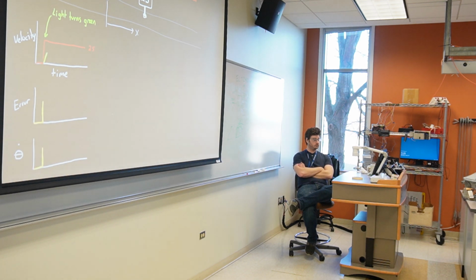Now, as your velocity increases towards 25 miles per hour, your error gradually gets smaller and smaller, so you gradually slow the rate at which you press the gas pedal. And eventually the car reaches 25 miles per hour, and since the error is 0, you stop adjusting the pedal and you hold it constant. Now at this point we can reason that with proportional controllers, the steady state error will be 0.